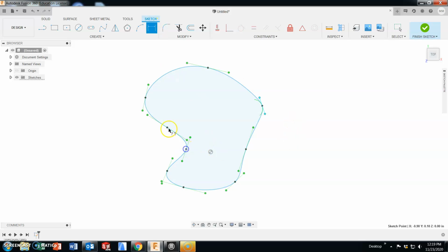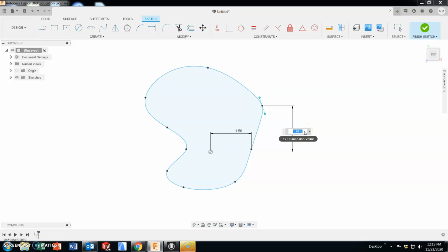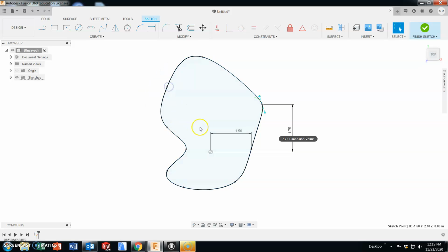In terms of a sketch, I can dimension from each node vertically or horizontally from one point to another. I could reference the origin and set a given distance. But typically with the freeform sketch with the spline is that you are not looking to create too many points of dimensional accuracy. You're really using it for the free-formed capabilities that it can create. So even if I set a couple dimensions here, I can come in and move the other ones. Whether I cut or extrude this or join this to another body, but that is the spline tool.